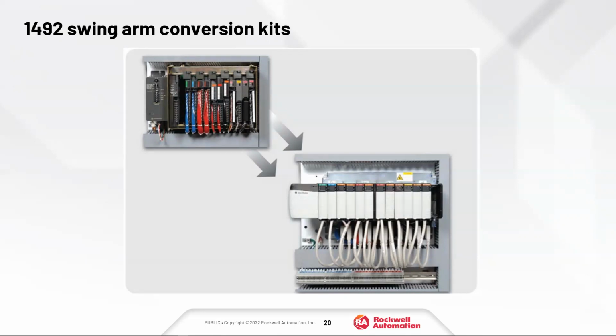And then those gray cables you see going into the new ControlLogix IO modules plug into the conversion rack. So you have a direct conversion on your IO, without having to lift and land any field wiring.